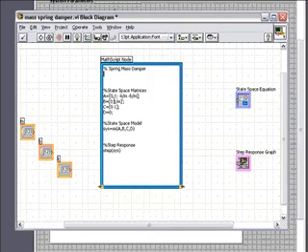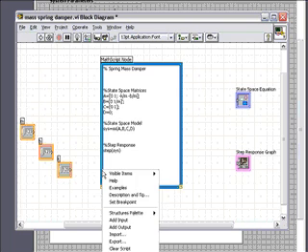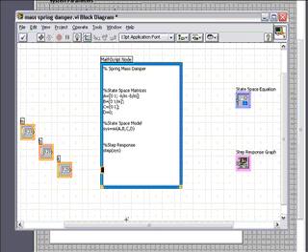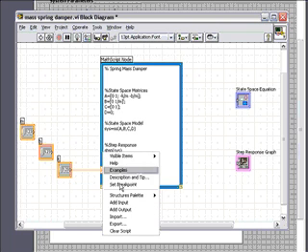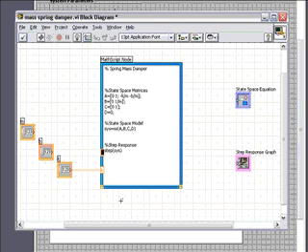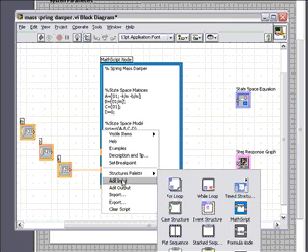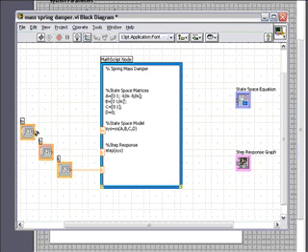And first I'll delete these system parameter constants. I can change these parameters on the fly if I wire them to controls on the front panel. So now I need to create an input to the MathScript node for the system stiffness and wire it to its control here. So I'll just put K there and wire it to this control icon. And I'll do the same for damping, and the same for mass, and wire them to their corresponding controls.